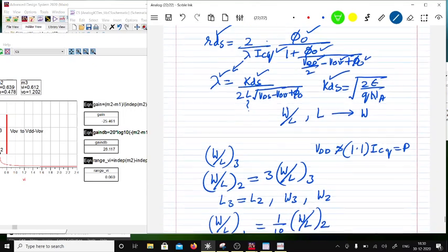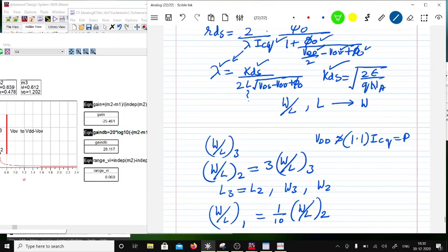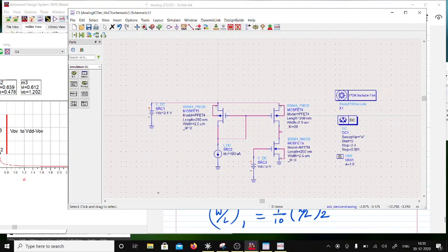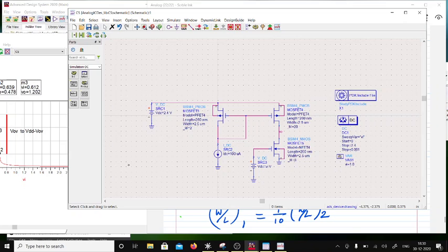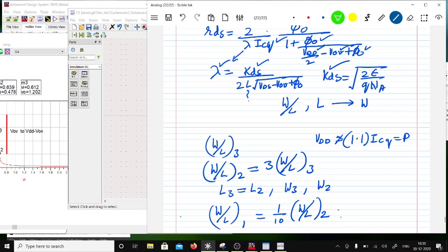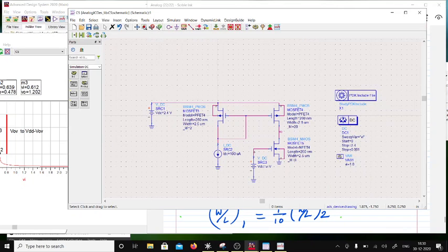So what designers often do is trial and error. That's what I did at the start. I just did this trial and error, and I got the 25 dB gain. I can start the other way. I can start with power dissipation and swing and gain, and then achieve the sizes. So both are possible. You can write a MATLAB routine to do synthesis. Just give it the gain, swing and power, and you will be done. So one is analysis, the other is synthesis.